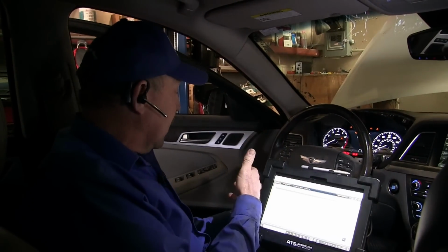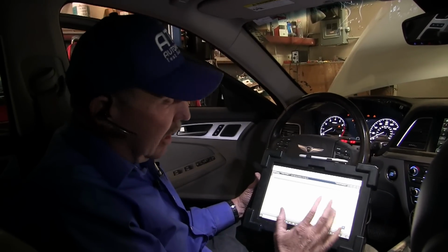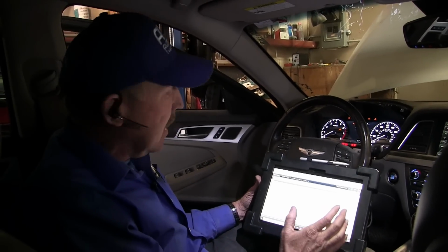So if I put a breakout and I think that I'm on the bus and I look at those signals, I'm going to have good signals. So be really careful. You always got to understand the topology whenever you're working on one of these systems. So if you went and you looked at the breakout box and you look at the signals off of it, you're making a vast mistake. You're not even looking at the bus structure that you need.